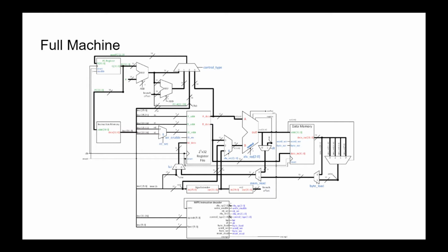But then also, because every MIPS instruction is 4 bytes, it's always going to be the case that whatever instruction we're jumping to, it's going to start on an address that's divisible by 4, right? Because address 0 would be a valid location for an instruction, so would address 4, but not addresses 1, 2, or 3. And similarly, not addresses 5, 6, or 7, but 8 would be valid. And so, since we know that the target is always going to be a multiple of 4, and we also know that the current value of the program counter is a multiple of 4, MIPS doesn't waste space storing those 2 bits that are always zeros.